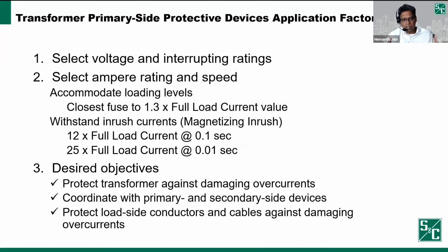So what I have listed here is a summary of all the application factors that we looked at. And I have an example in the next slide that shows plots using a software that we have called Coordinate, which is available on our website. You can plot the various transformer curves, fuse curves, and other manufacturer device curves, see how they coordinate, and make your decision using the TCCs that are in the system.